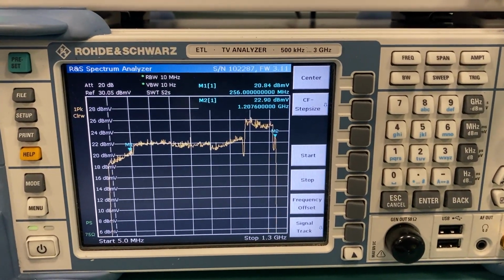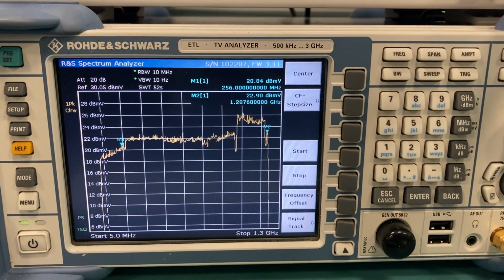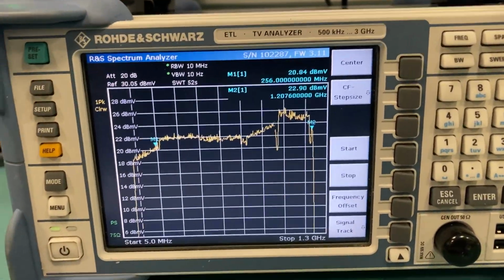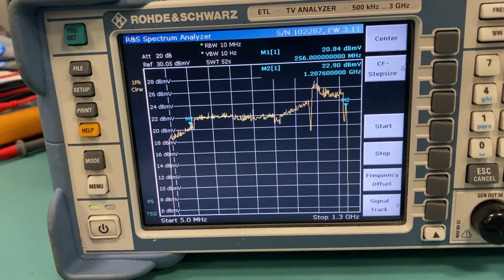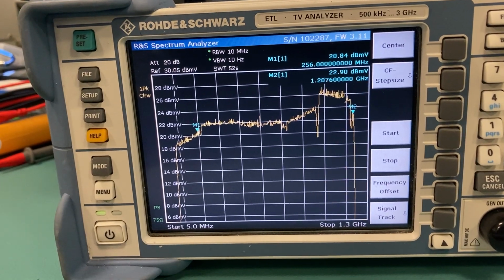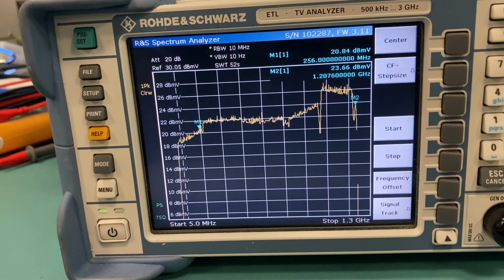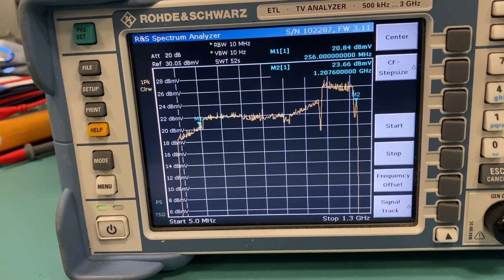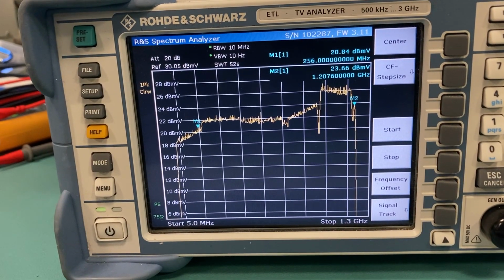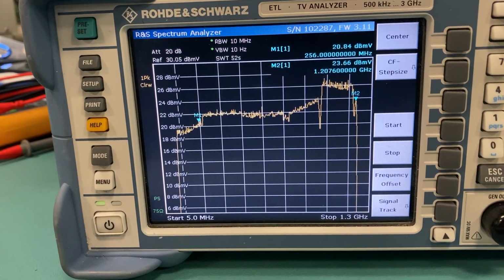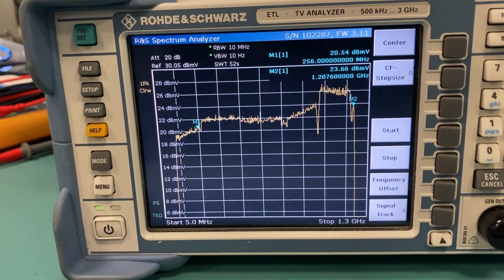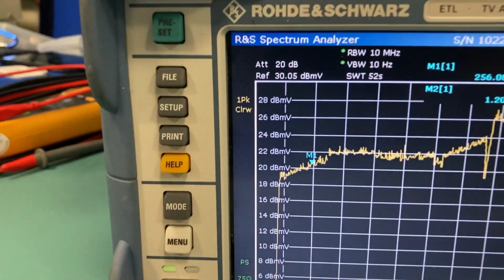Let's go the other way while it's measuring. So this is now going in at -1, and we'd give that a while just to go across the screen. But essentially, what you'll see is there shouldn't be any major gain changes there because we're within the automatic gain control range of the ONU. Just let me update the left-hand side of the screen. Nearly there, and that little step where marker 2 should disappear, and there you go, it's disappeared.